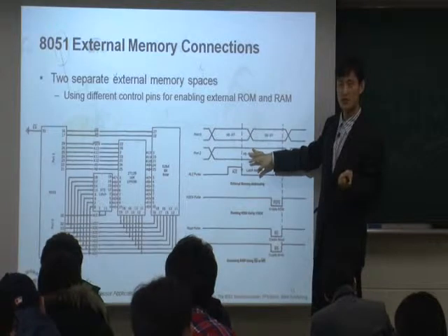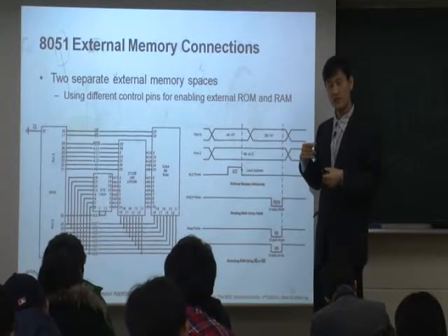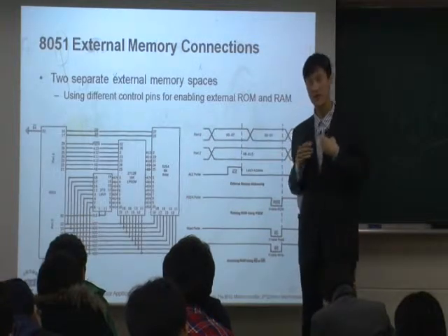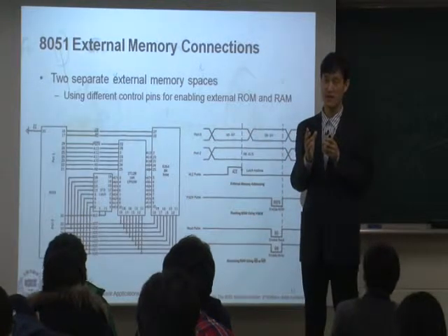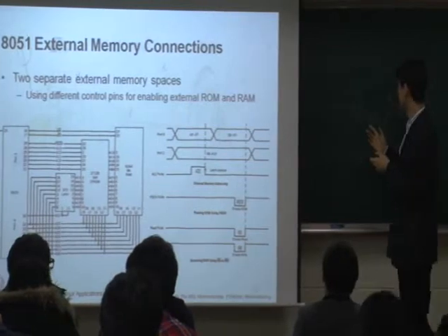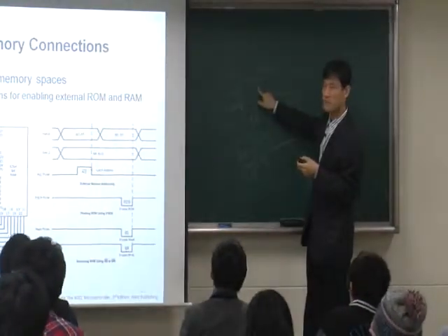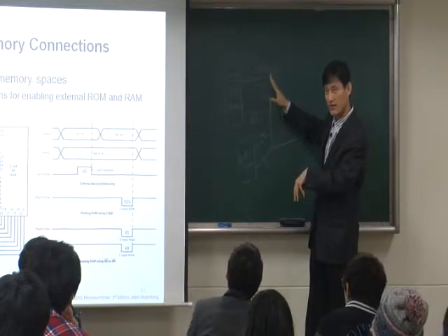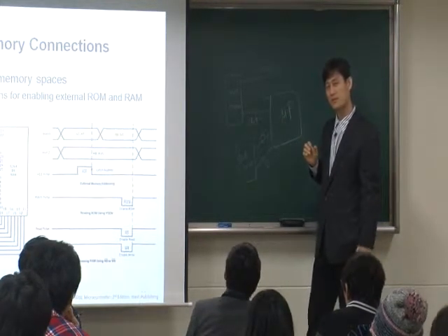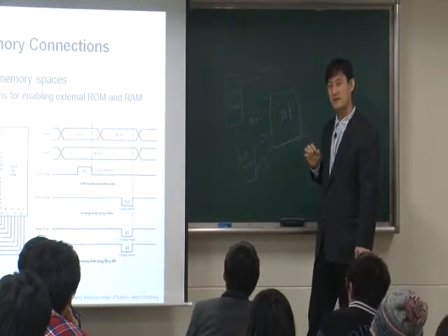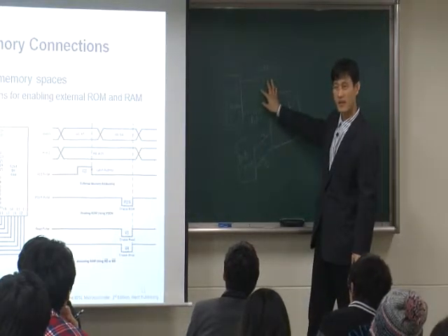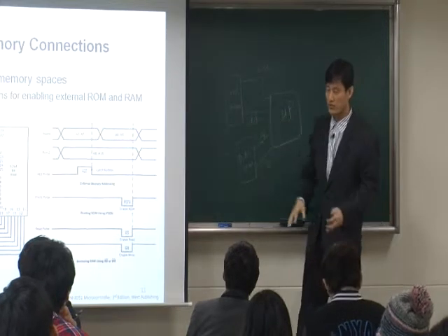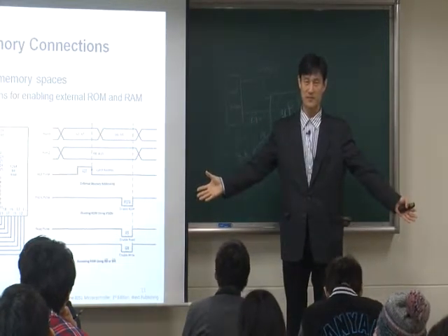30, 40 years ago. If you go to 30 to 40 years ago, then this processor was probably very expensive at the time. And if you want to have address pin and also data pin separated, right? Then what's the problem? You need so many pins. You have 16 for address, and you need 8 for data, right? So we need so many pins.